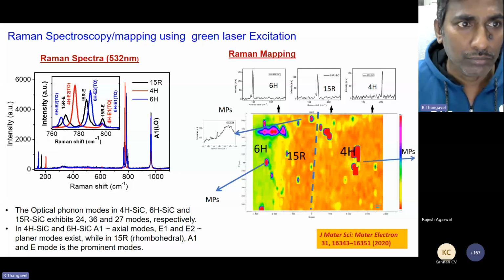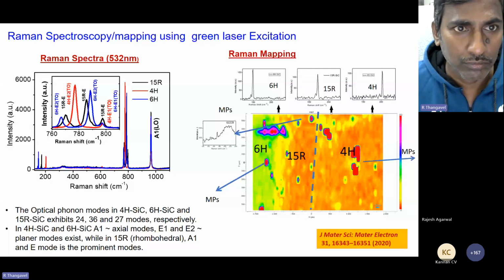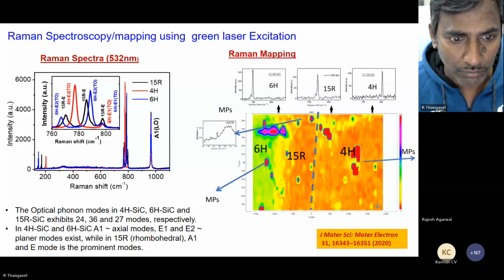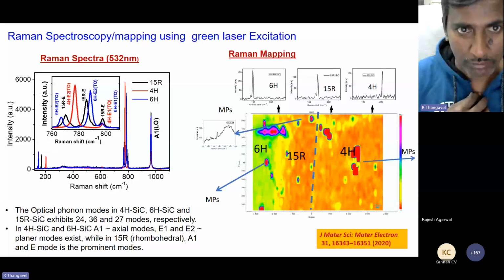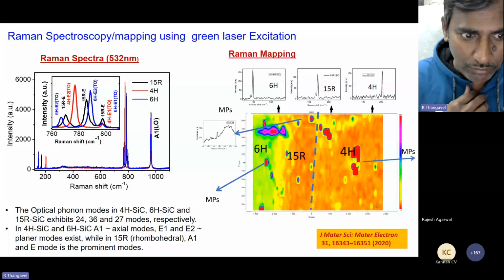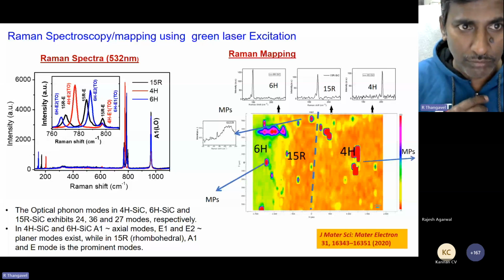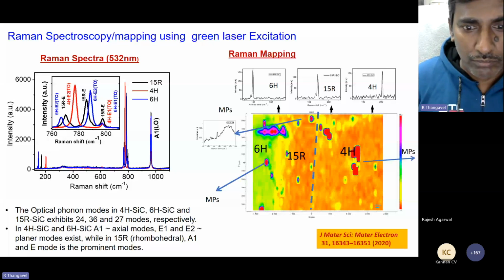After cutting, the X-ray pole figure measurement was done again, and we found that these 4 peaks are as expected. By just taking the proper tilt angle using the X-ray pole figure method and the rotation angle, the crystal has been cut, and we found that the crystal is highly oriented along the 100 direction.